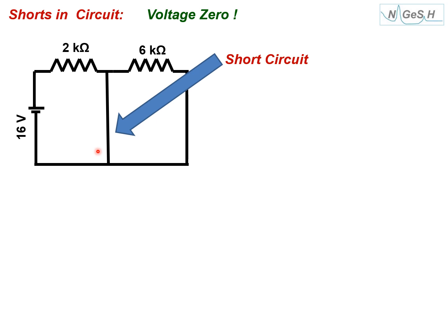Now I want to know what is the voltage across this. Of course, I have written here. It is 0 because resistance is 0. Now, what is the current flowing through this? Here you should know that once you have short circuited, generally you need not see what is there on the other side, because if you calculate R1, R2 by R1 plus R2, R1 is 0. Mathematically, it is 0 resistance. And otherwise also, once you short circuit, current finds the lowest resistance path here.